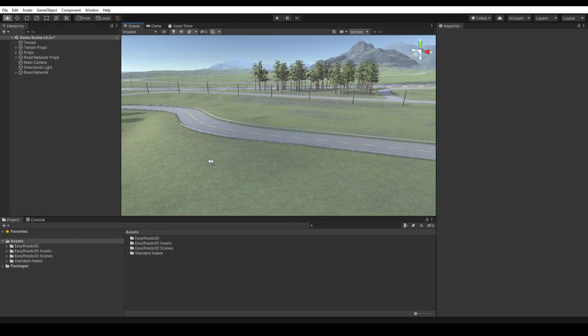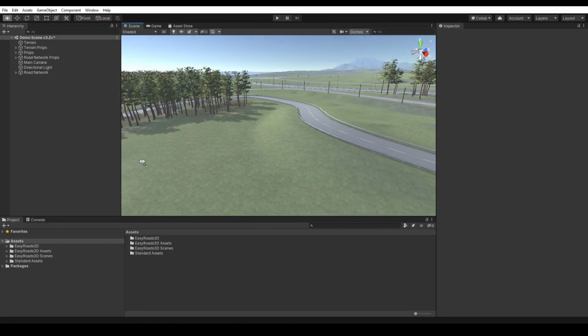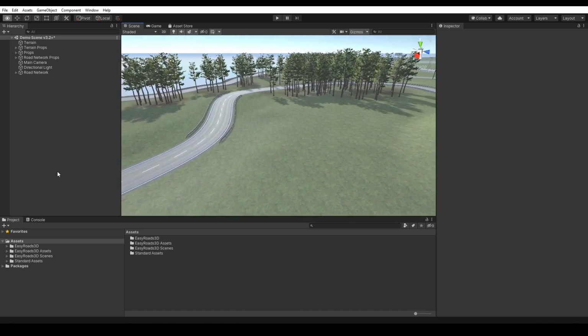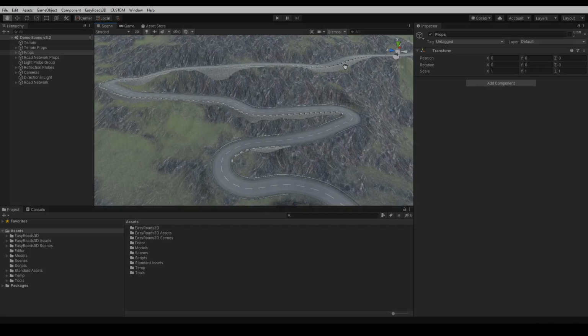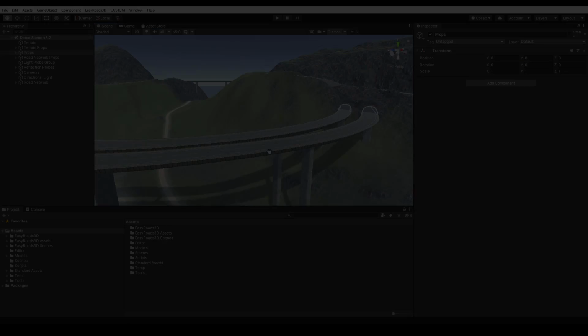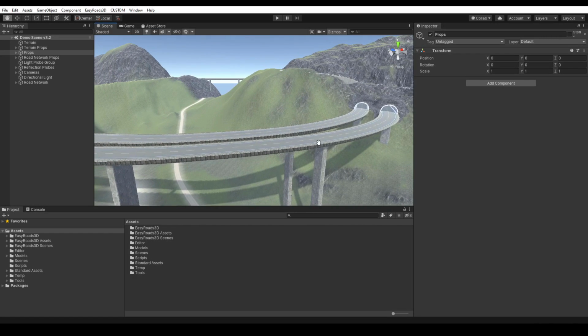In these videos, we saw that side objects can be activated along the full road, or on specific road sections, and that they can be generated based on rules taking into account the road shape and terrain profile. This last option is very useful to effortlessly and easily auto-generate, for example, retaining walls and bridges in those areas where that suits the road and terrain profile.